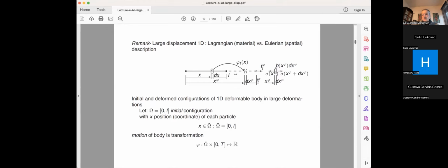If the deformation is homogeneous, you can call this stretch, which is equal to the ratio between L_phi and L, L_phi being 2 times as big as L, that means stretch is equal to 2. So if I take a piece of rubber and I stretch it 2 times, I really introduce very large deformation where stretch is equal to 2.